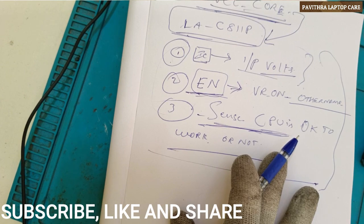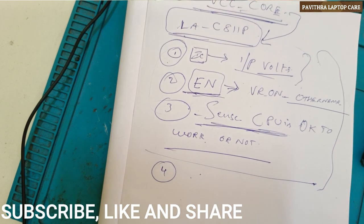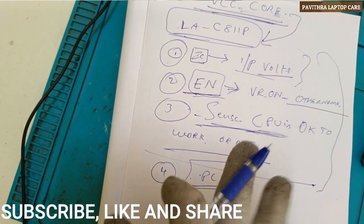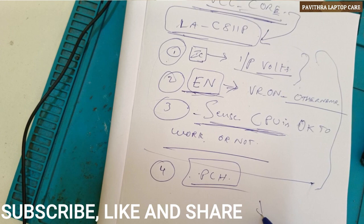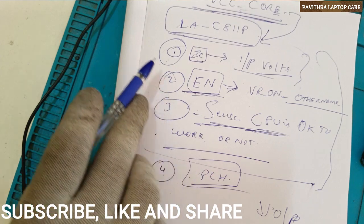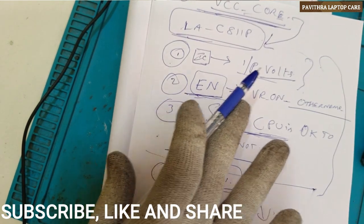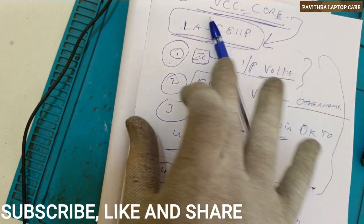One more thing: from the PCH also some voltage or signal will come, then it will start working, and only then finally we will get output. If after getting input, enable and sense you are still not getting output or it's not triggering, then in some conditions we need to replace the IC and then check. These are all basic things.